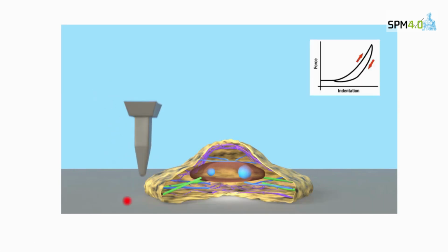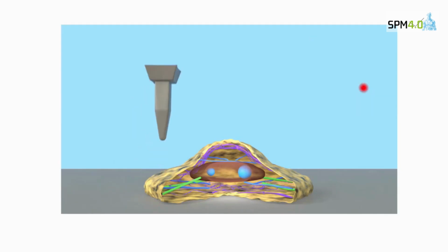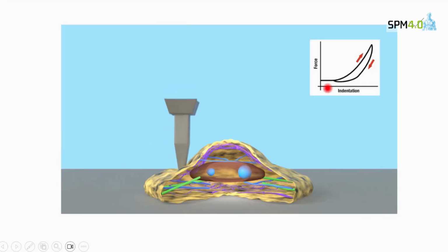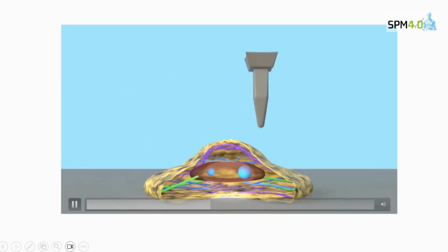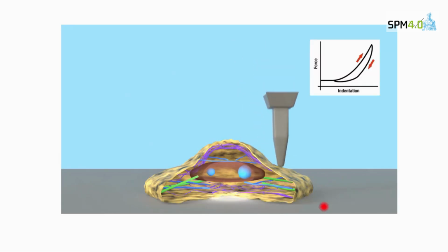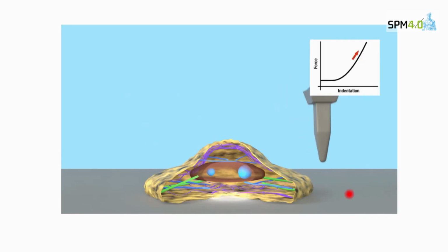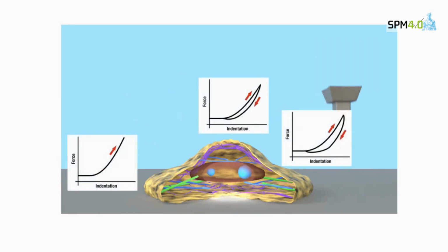Have the tip, and we are just interacting and getting force-distance curves. And the force-distance curves depend on the region of the tip. In this way you can get nanomechanical maps, which was what we put the basis of yesterday. And of course, the idea is to get these force-distance curves, and the force-distance curve has a signature of the local region that you are exploring.